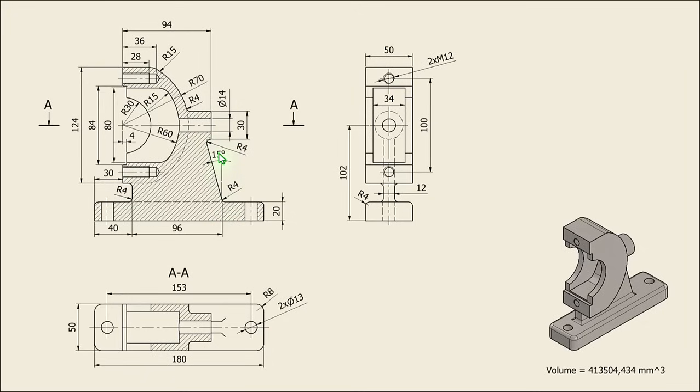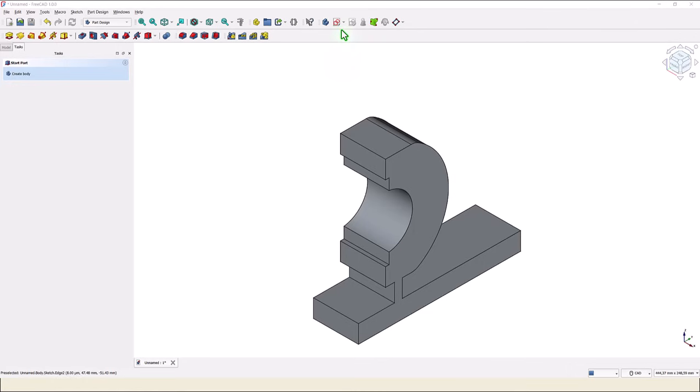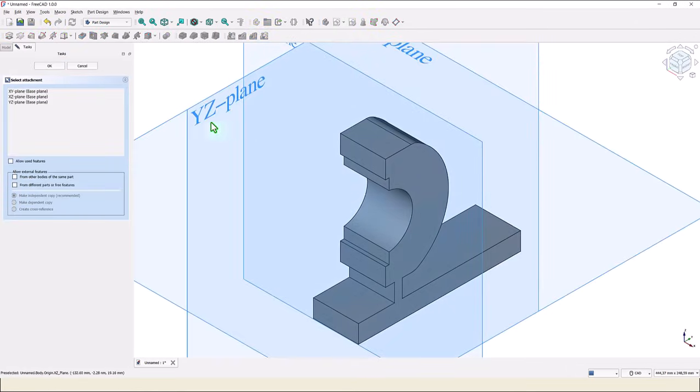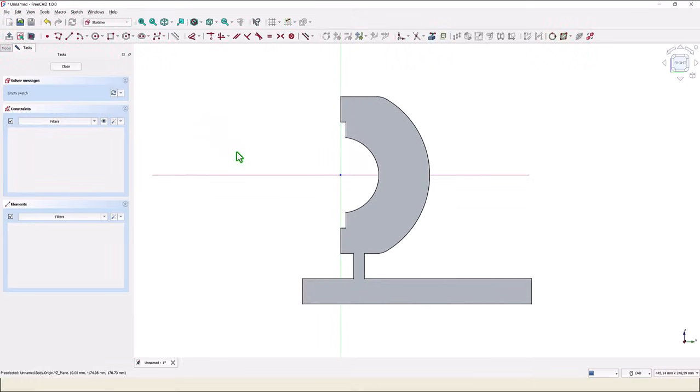of 15 degrees, 96 distance. We'll continue this line to here and to the existing contour. We select this plane once again, mid-plane. We apply C inside and we project some entities. This one, and this one, and this one.